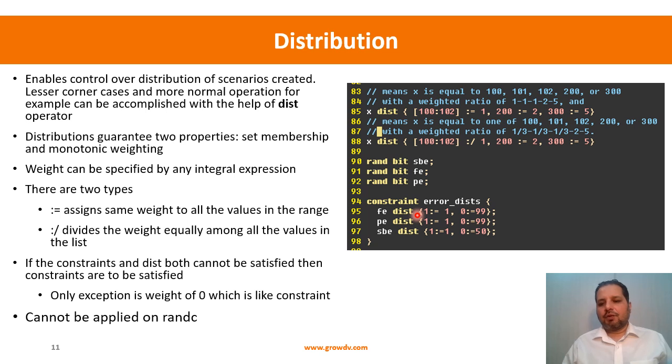So this way you are covering error injection, but you are prioritizing the normal operation. Now the other thing that you want to note is that the distribution may not remain the same throughout the project. During the beginning of your project, you want to focus on the normal operation and the critical areas. Then if you are able to satisfy them, towards the end of the project, when all the critical items have been met and are satisfactory, and if there is still time, you can change the distribution such that you start focusing on the next priority areas. So you can increase the error injection and then test with more error injection capability. Initially you focus on normal operation and make sure the normal operation is all okay. If the normal operation itself is not okay, then what's the point of verifying with error injection?